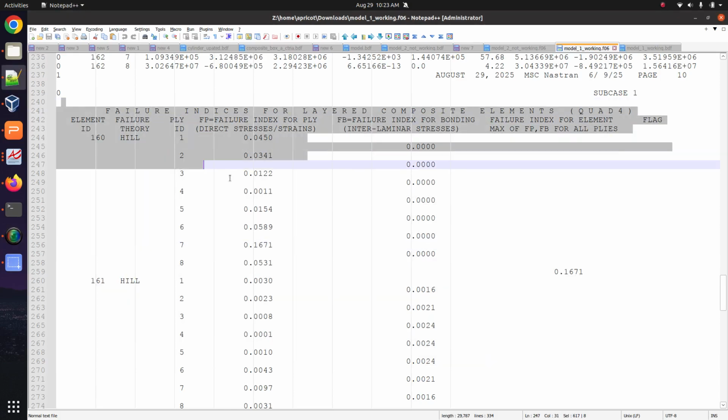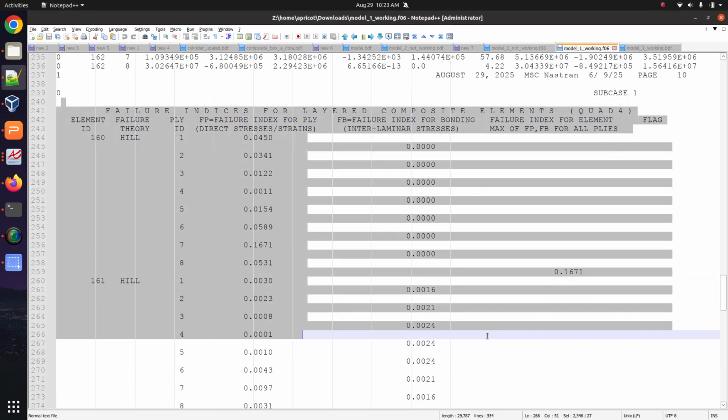In this video, we are going to talk about how to output the failure indices from MSC Nastran. Now, the failure indices are output when you use PCOMP or PCOMPG entries.